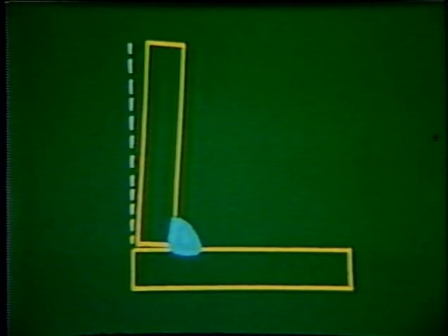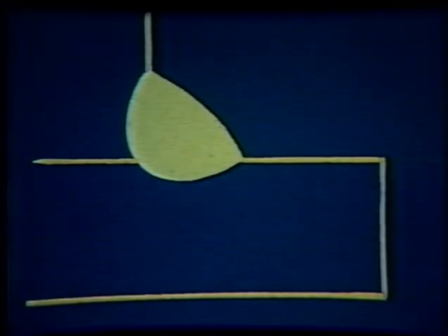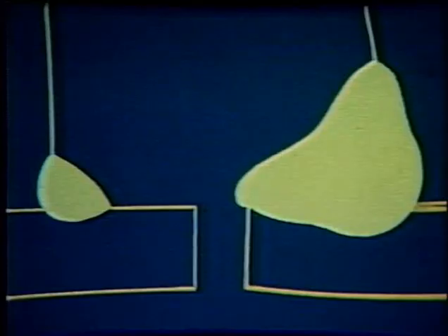Shrinkage of the weld during cooling can cause various types of distortion and dimensional changes. If this is to be minimized or prevented, strategies must be used to overcome the effects of the heating and cooling cycles of the weld. This should be done both in the design stage and in the shop during fabrication. One strategy is to keep the shrinkage forces as low as possible by depositing only the amount of weld metal that is required by the procedure and indicated on the drawings. Do not over-weld.